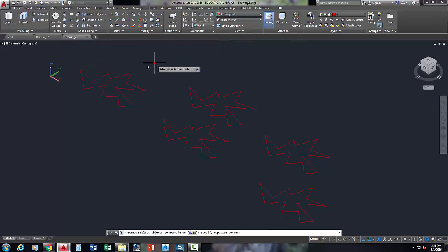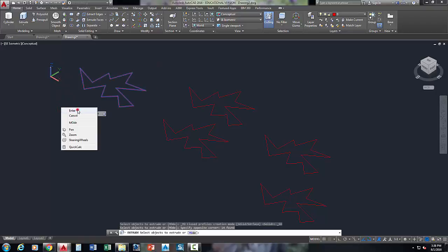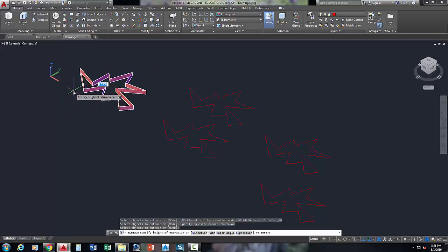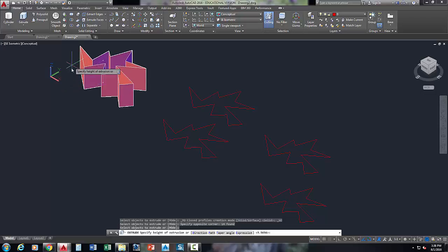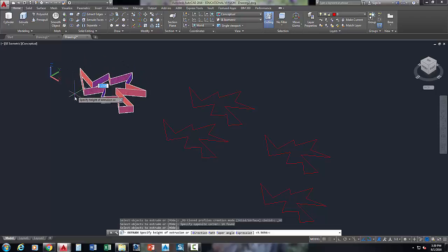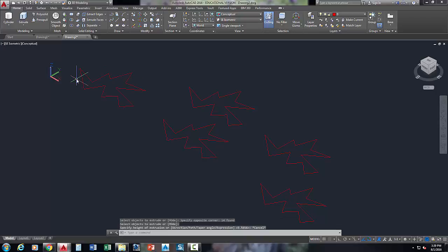If I want to extrude this object, it's extruding it. It's actually making it have depth along the z-axis, but it's not what we were looking for. This is just building up walls, or just the outline of the shape. It's giving thickness to those lines along the z-axis. So the extrude command used to not work at all, but for the last few releases it started doing this. So it sort of works, but not the way we wanted it to.